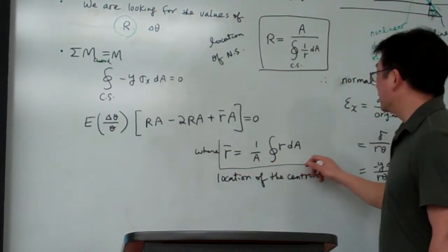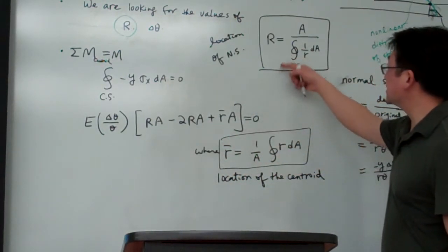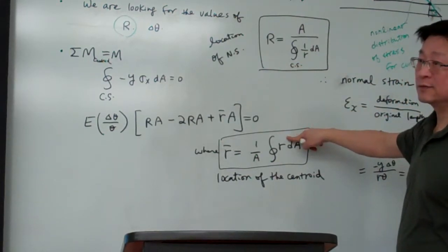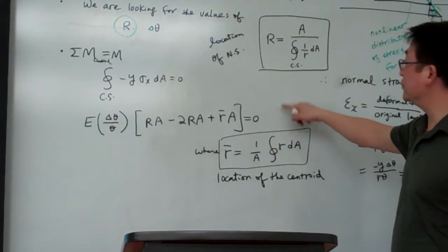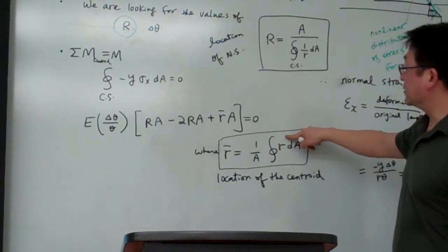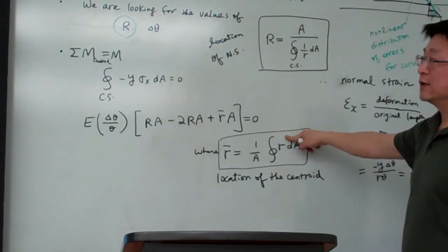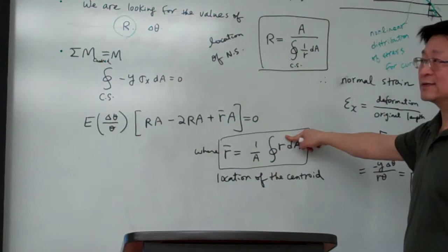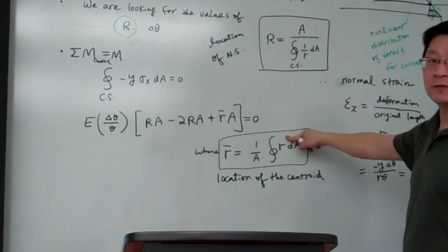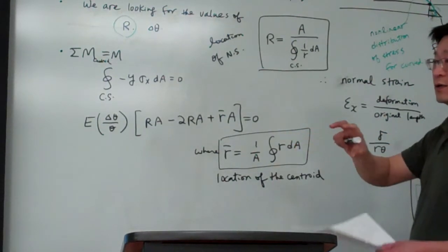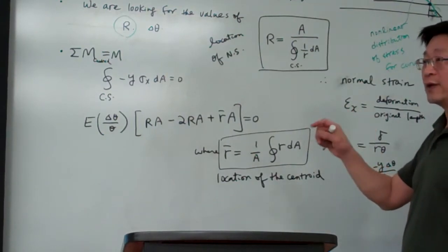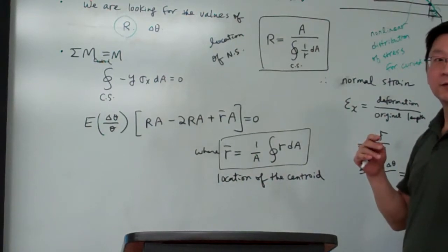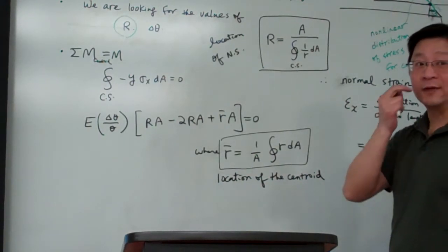And for the curved beam, in general, the two quantities shouldn't be equal. So from the two equations here, the first thing you have to bear in mind for the curved beam is that the neutral surface in general won't pass through the centroid. Before, in our uncurved beam, once we identified the centroid, the neutral axis passed through the centroid. You remember that one?